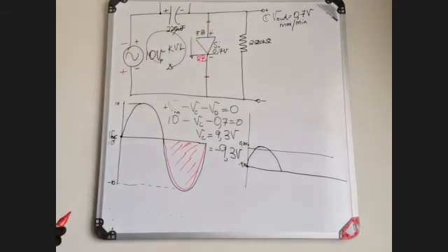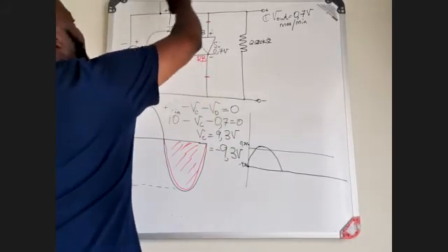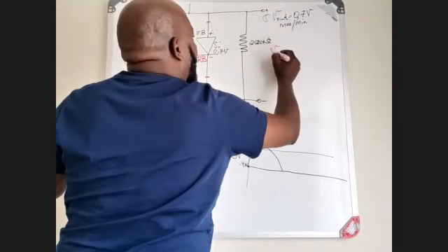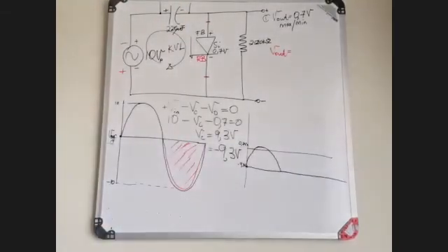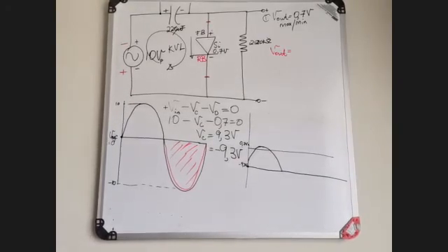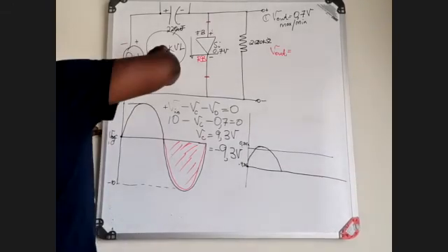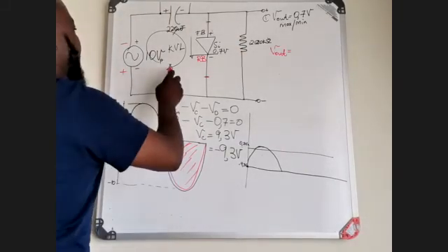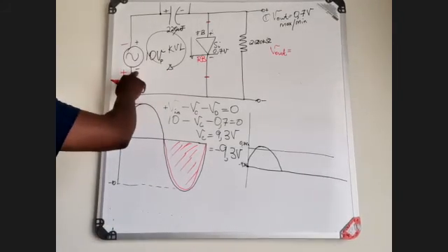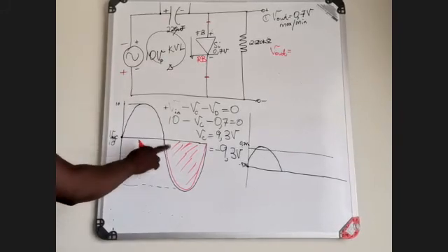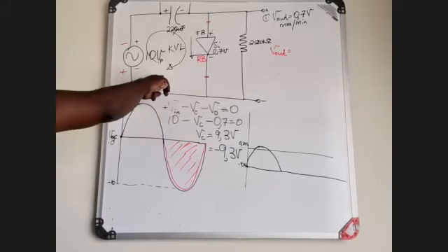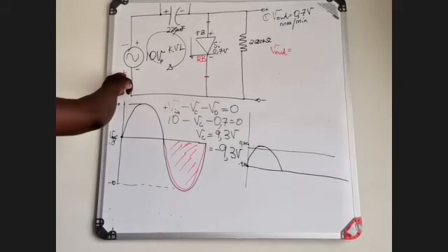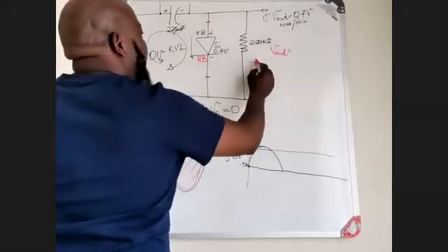If that is just an open wire, then your current is moving within this component here, not looking at this. For the voltage of your V out, you need to follow the KVL. The KVL is established in this direction, so I'm looking at this source not from the negative, but from the positive, because the cycle has changed. If I'm looking at this from this side, what will be your input? In this case, now the arrow is facing the positive, which means now it's minus V in.